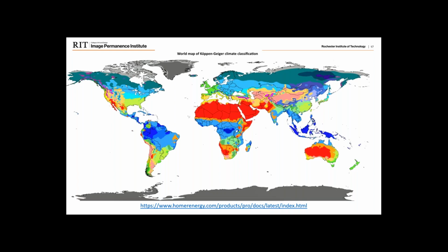We drive home the thought a lot here that whatever happens outside eventually becomes your inside air. And that it's very true. Even if your mechanical system, every mechanical system uses some amount of outside air. If your mechanical system is using 5% or 10%, it still has some effect in your collection space. If it's really dry outside, you'll have dry periods. You'll notice your dew point goes down inside your collection space. If you have really heavy rains, you may notice that your dew point may go up in your collection space, even if you're using a small amount of outside air in your system.